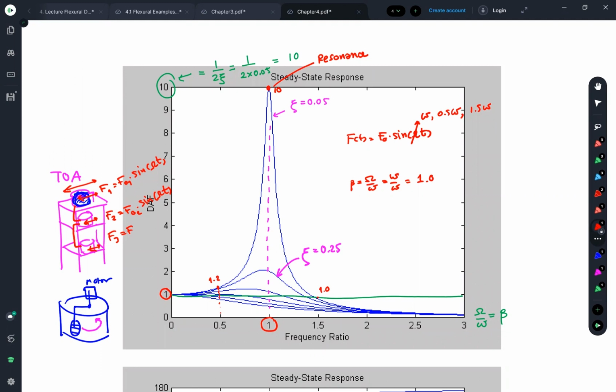But this idea, I think, even though theoretically good, practically is not so good. Because I have to put heavy mass on the top floor. If I put the mass on the second floor or on the ground, it has no such effect. I have to put it on the top floor, right? And that raises a question about the safety of the building. You increase the axial load on the columns. That is not good, right? And the foundation is already constructed.